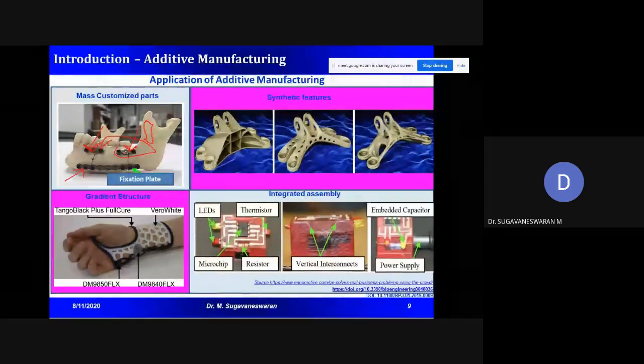You take a sheet or a plate, cut the profile using a laser, and put in drill holes as per your requirement for fixation. Then you can fix it. So in both ways it is possible, right? In this case, it is a titanium material, which is very difficult to machine through conventional manufacturing processes. So we need a different type of processing technology. That is one case: the material is difficult to process.